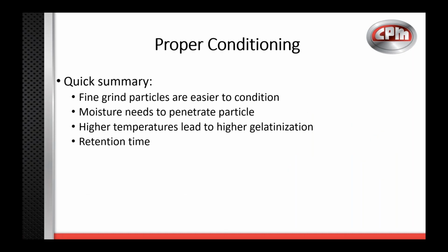So to sum up what we just talked about before we move on, the finer the grind, or the finer the particles, the easier it is to condition due to less distance that the steam has to travel to penetrate. But we want that moisture to penetrate to the center to add that heat for our starch gelatinization. So as you see higher temperatures, that usually leads to higher gelatinization factors. But that all really just comes down to time. How long is that product in the conditioner?